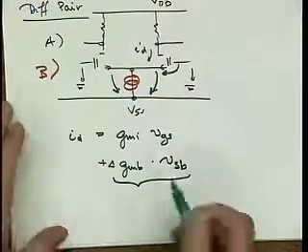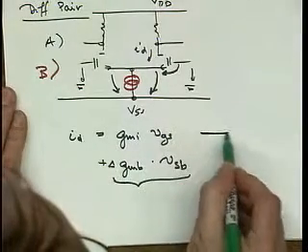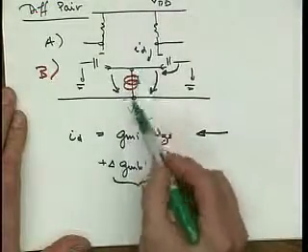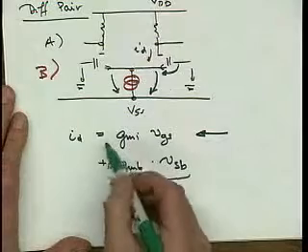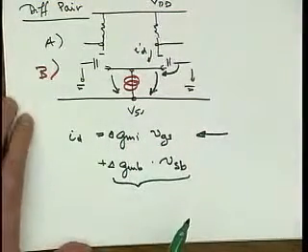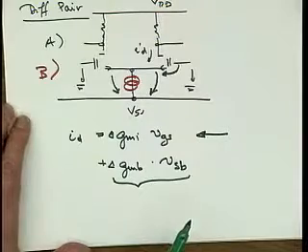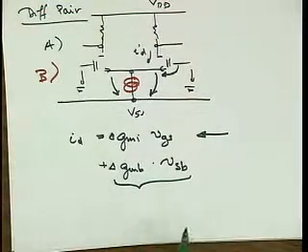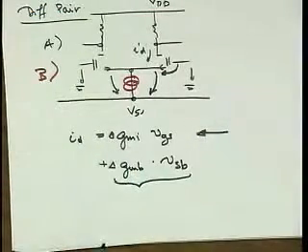So then, if I make an arbitrarily good current source here, I can make the error from the delta GM arbitrarily small also. But I cannot do the same thing for this guy here, the GMB transconductor, because it doesn't even see this current source. Making this current source better doesn't help it at all, right?